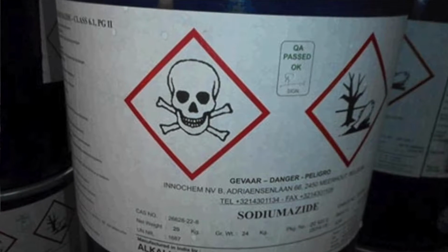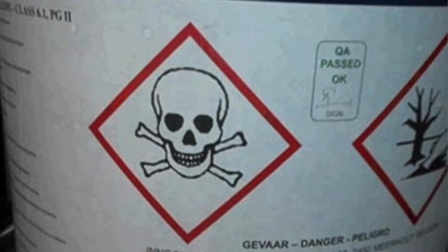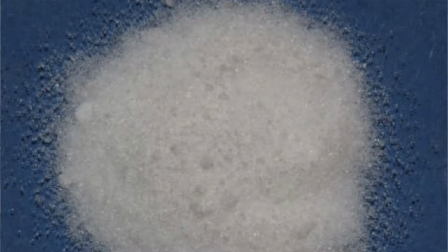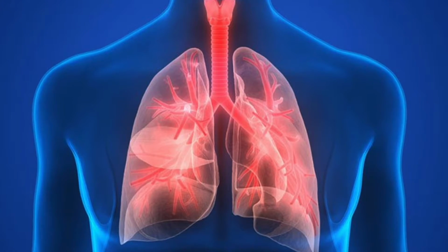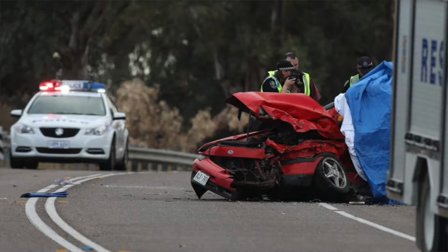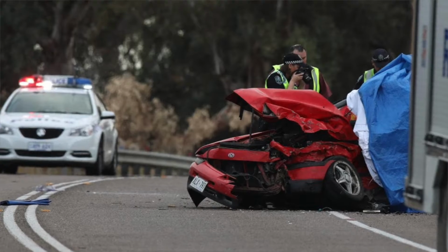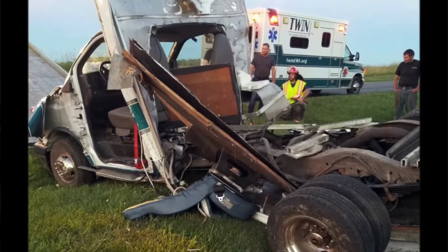We need to be very careful of how we handle airbags, because sodium azide is odorless. It is very dangerous for the drivers because it is very difficult to detect. After reacting, one of the products besides the nitrogen gas is a sodium metal dust that can spread easily in the car after the explosion. If the space is very confined, the sodium fine dust can be breathed by the passengers. This will eventually get into the lung alveoli, causing asthma or intoxication, and even weeks after the explosion of the airbag, it can trigger pneumonias or cardiopulmonary failures. Also, it may be very dangerous because if the driver loses consciousness, it may take time for help to arrive at the place of the crash, leaving the driver more time exposed to the fine dust.